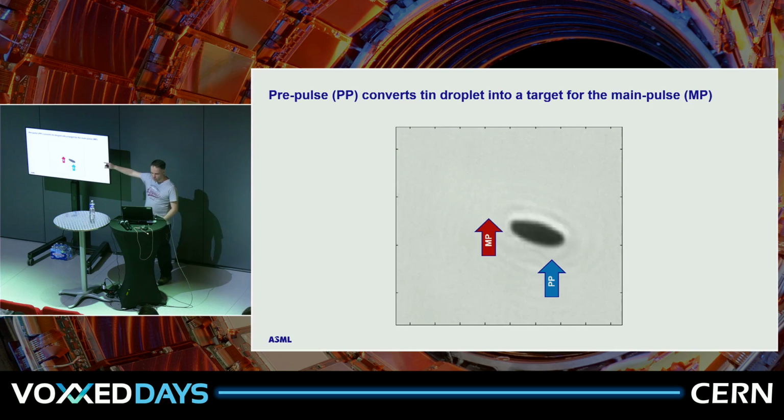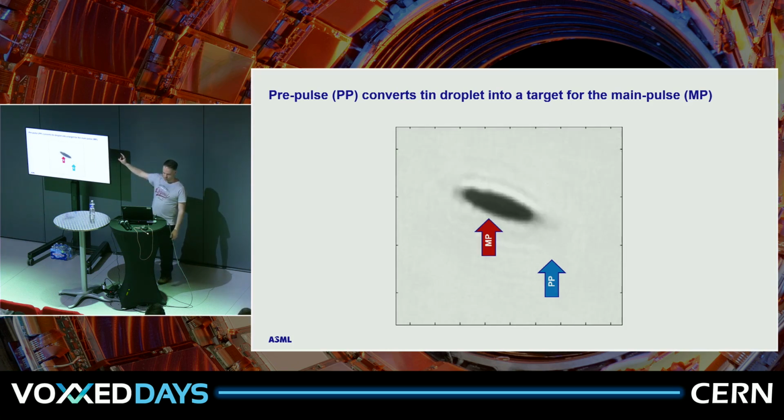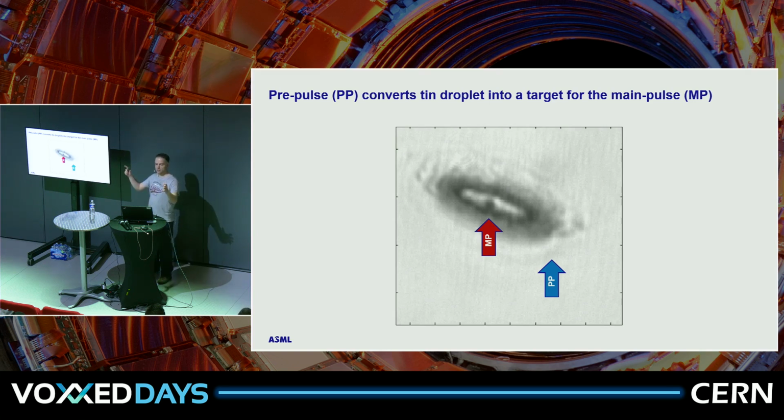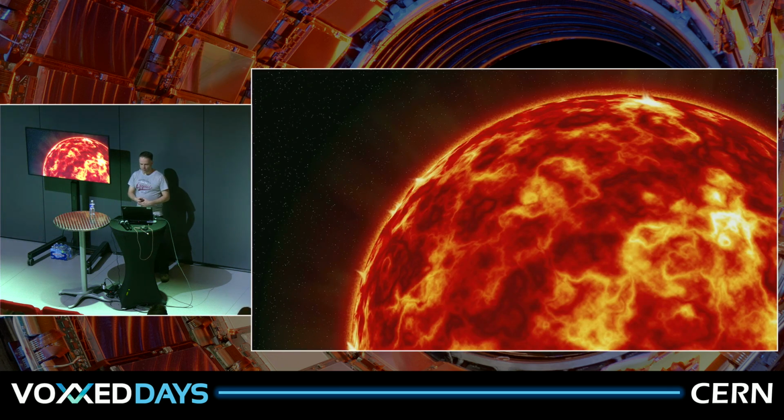Looks a bit like this. So this is not a UFO or something. You saw it being hit once. Now it's about to be hit for the second time, and then it emits the EUV light. And that resulting plasma has about the temperature of the surface of the sun, so we use gases and stuff to then again cool down the temperature, but need to remove the gases quickly, because then the next laser, of course, will shoot. So to do all that 50,000 times per second requires quite some calibration and figuring out.